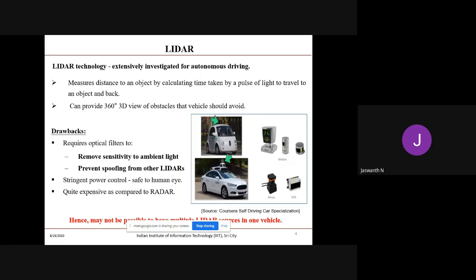As you can see in the figure, the arrow mark represents the Velodyne high definition LiDAR, which is commonly used in Waymo self-driving car. And the major working functionality of this Velodyne is such that the LiDAR unit emits pulses of laser light, then the laser beam hits an object and the pulses get reflected back to the LiDAR unit. And then the LiDAR unit processor measures the time it takes for the pulse to return, which translates to a measurement of the object's distance.